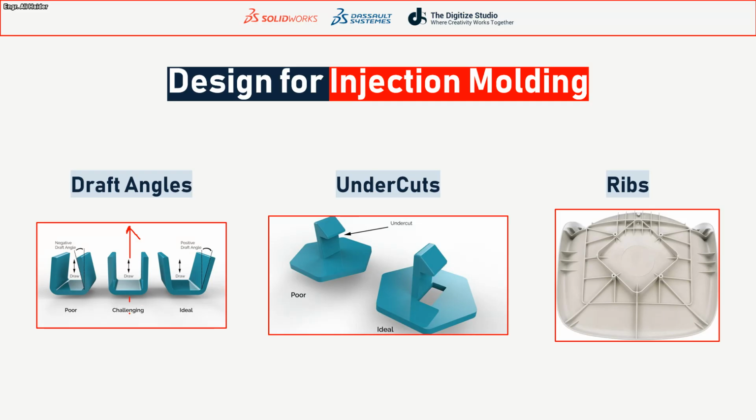Similarly, when we push the ejection pins and push this part with the help of the ejection pins, the outer face also causes surface friction against the cavity side, and the part will have some marks on it. So we should avoid that.